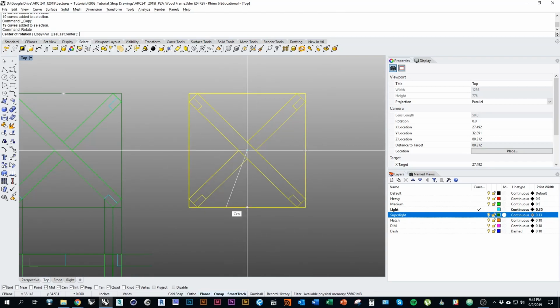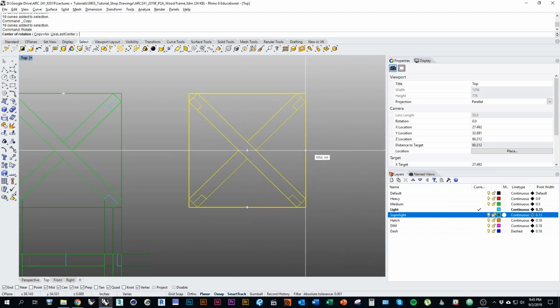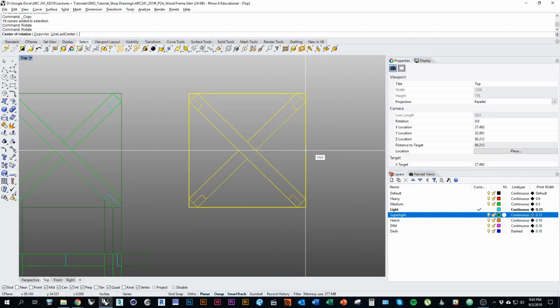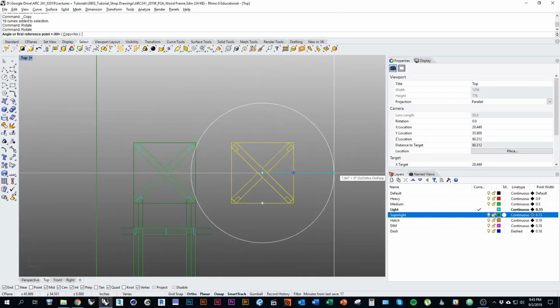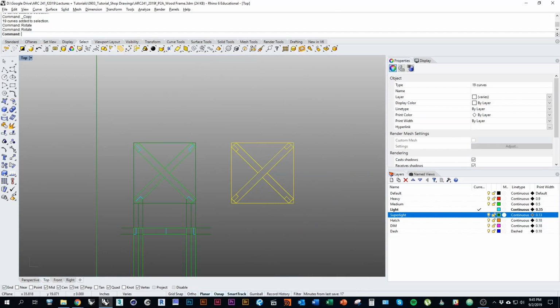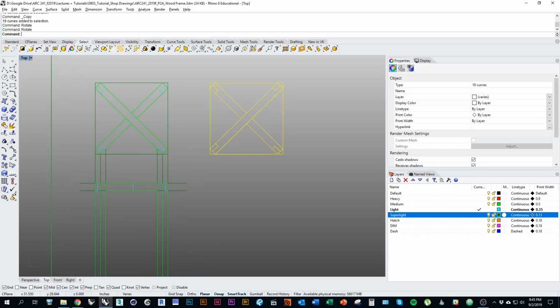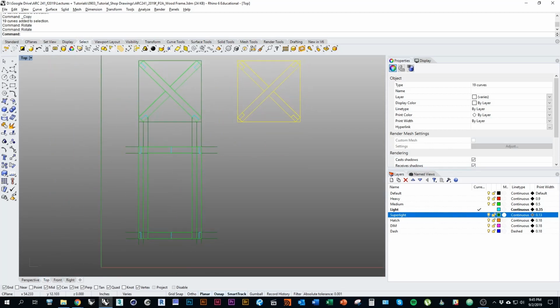I can use the rectangle as the center point and get the center point snap to the center from that. Or if I have Smart Track turned on, I can make a Smart Track point at the outside midpoints. Again, just snap to that midpoint, wait till it turns gray. Okay, and then Smart Track will find the intersection. I'll hold shift, rotate it 90 degrees. Okay, and then we can use this to define how we'll show the joints on the next elevation.